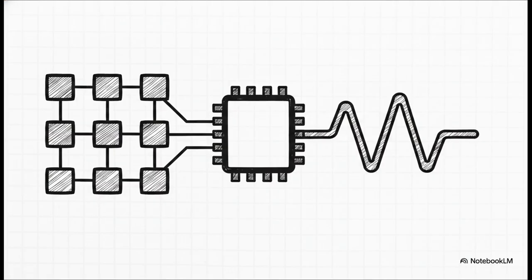But how do you program that organic grit into rigid digital steps? Well, the developers didn't try to make the math perfect. Instead, they mathematically modeled the actual imperfect physical components. It is absolutely wild how far they took this. We're talking about writing code that meticulously emulates asymmetric coefficients, the specific soft clipping saturation of silicon diodes, and a high-pass filter in the feedback path. They intentionally code in what they call analog drift, deterministic variations in voltage bias that make a square wave slightly lopsided and nasal. They are using advanced discrete math to painstakingly recreate the exact hardware imperfections the industrial engineers were desperately trying to get rid of.